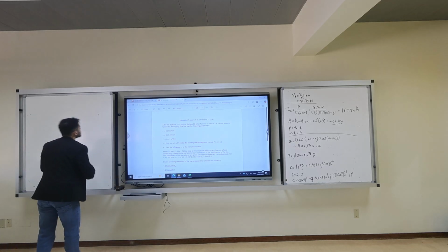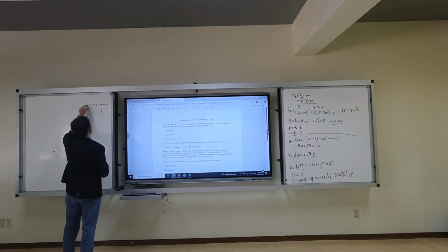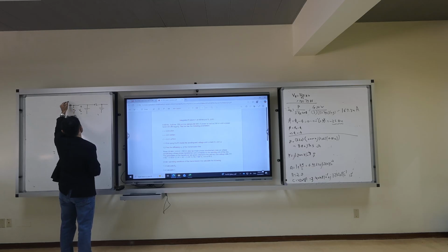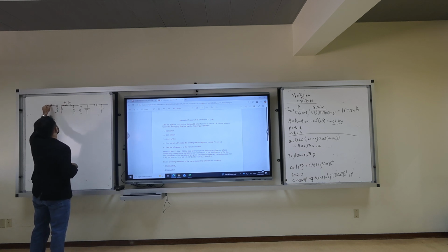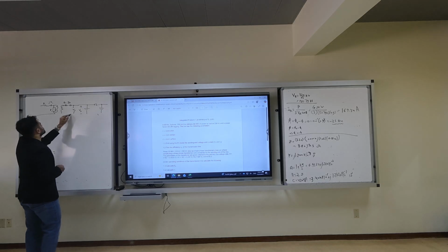So what is the original circuit? The original circuit is I have a pi model. Here I have Vs, right? And then here I have what? Transformer. Vs. Here we have X2, R2, transformer, JX1. Here I have a parallel branch, RC, JXM, R1. You agree with me?